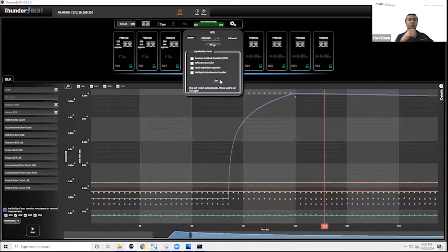And this is really one of those value adds that is really unique to MultiLane, in how much we can present with the BERT. So we can add real DFE, reflection canceller, level dependent equalizer, or even a multipath interference canceller to be able to replicate different equalization techniques that your DUT will be able to leverage out there in the field.